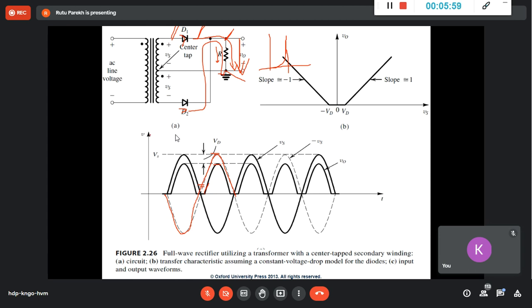And this is the voltage input output versus time. And this is your input voltage versus output voltage. And your output is following input after 0.7 volt. Okay, so up to 0.7 volt, whatever input you are changing, this Vs, your output is still going to be 0 volt. Okay, because there is no current flowing. This is not conducting. It is not reverse bias.